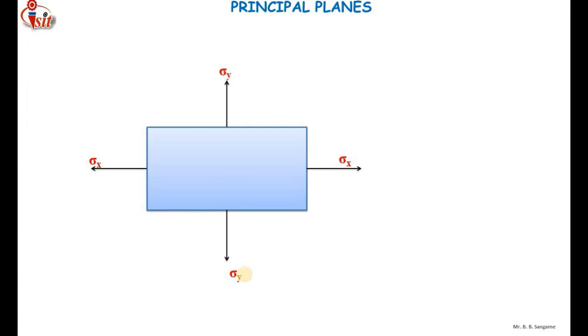Okay, so here you can see that I have applied a shear stress along the positive x-axis, but the shear stress is acting over the y area, so that is why it is represented as tau yx. So this stress is acting towards the positive x-axis, as we know that compressive and tensile stresses act perpendicular or normal to the area, but shear stress is the only stress which acts tangent to the area. Okay, it acts over the area.